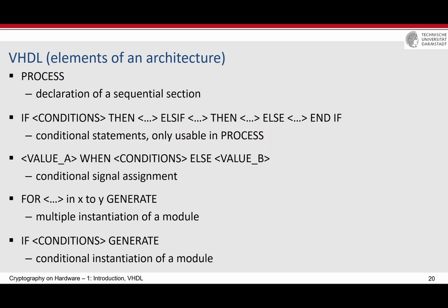Now, we will see this with examples, but you need to learn the process, which is similar to always in Verilog. Declaration of a sequential section. As I said, you may think if it doesn't have any clock, it's just a representation of the functionality of the hardware. If it has a clock, it's exactly the sequential operations which happens every clock cycle in the process, yeah, or always in the Verilog.